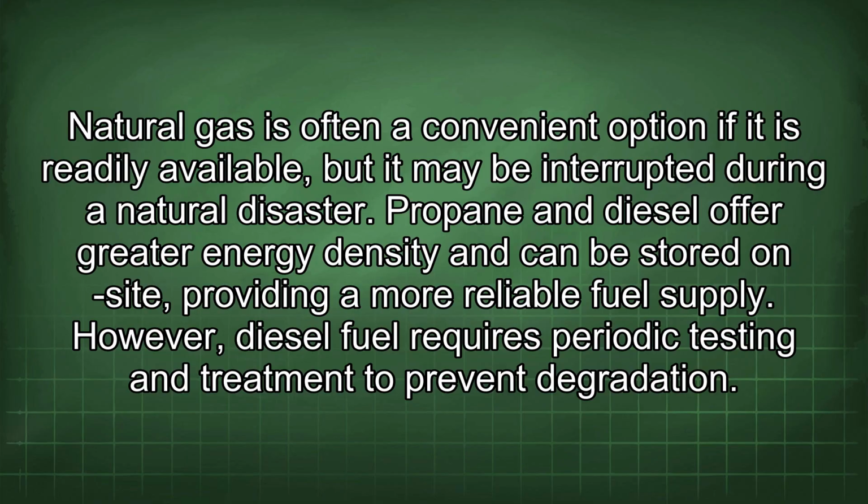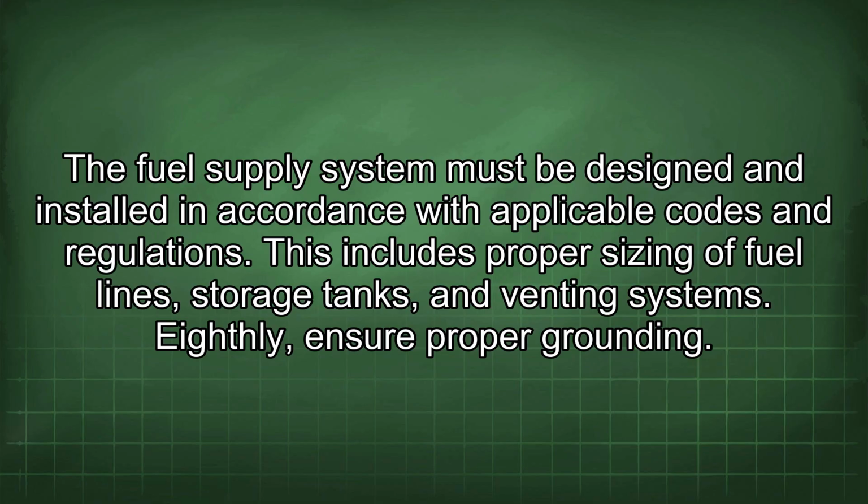Propane and diesel offer greater energy density and can be stored on site, providing a more reliable fuel supply. However, diesel fuel requires periodic testing and treatment to prevent degradation. The fuel supply system must be designed and installed in accordance with applicable codes and regulations. This includes proper sizing of fuel lines, storage tanks, and venting systems.